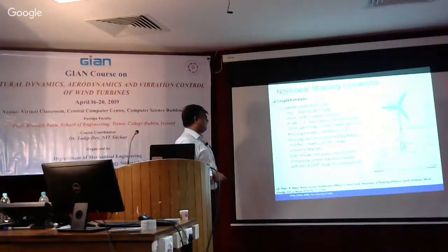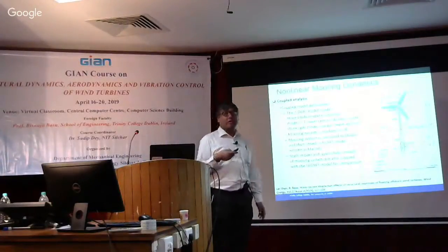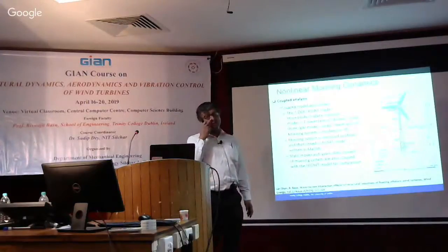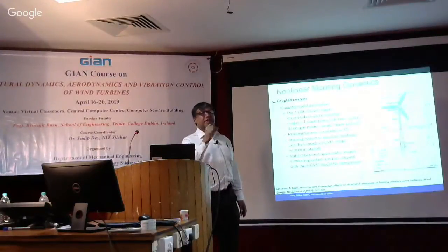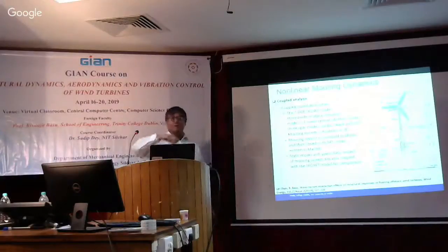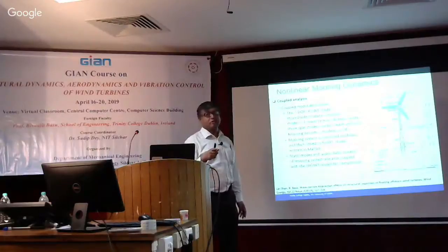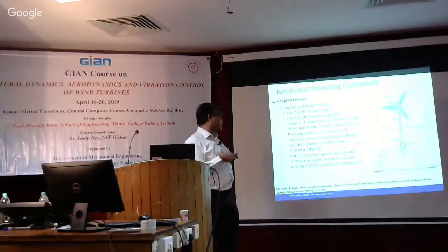And finally, I mentioned to you, you can look at this wind energy paper. We have done a full interaction analysis with floating offshore wind turbines, and the cables have been modeled by nonlinear analysis. We used our OpenMOVE code, and also used the MIT code, which is the MOVE code. Now, MOVE actually uses a lumped mass model. So in fact, ours is better than the MIT-developed MOVE code. Ours is a continuum model. Therefore, they cannot account for the current. The MIT code cannot be used for current interaction, whereas we can do that.